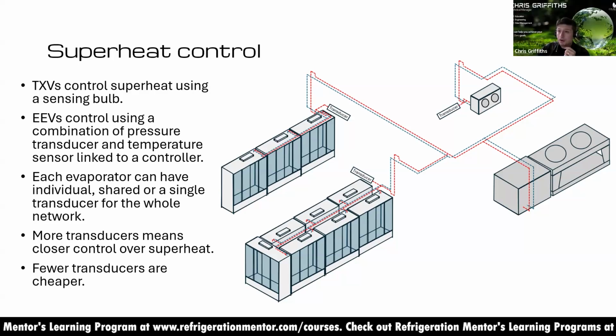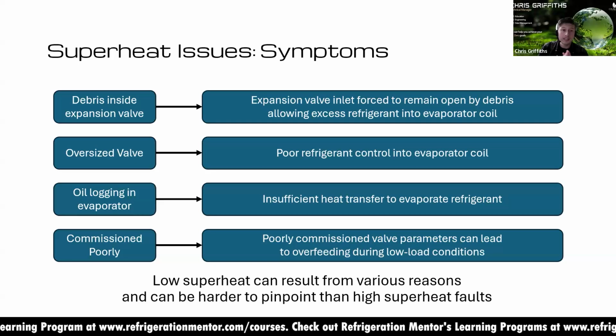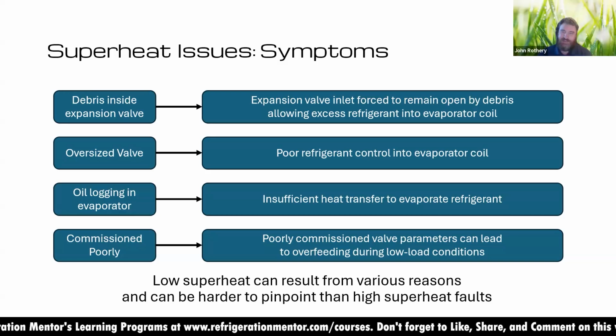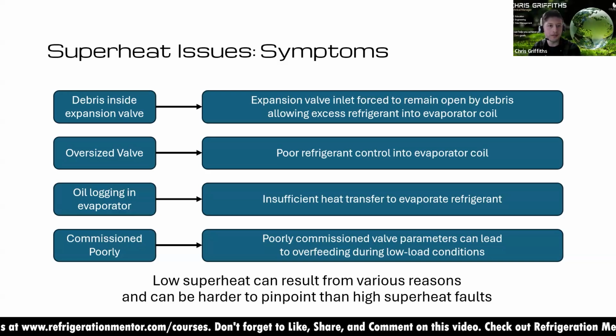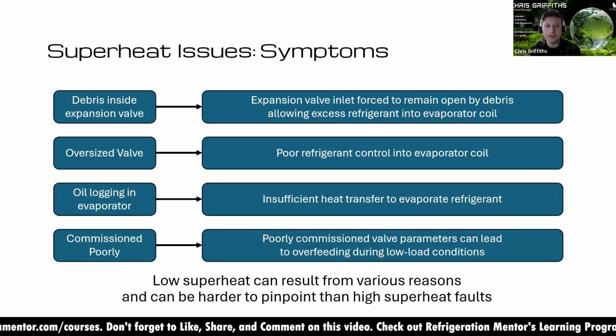Sorry, something just to jump on that, we'll look through it in a minute, but one of the issues we've actually encountered in the past is with those controls, sometimes it's buried deep in manufacturer's literature, but say you have a 60 bar transducer versus a 90 bar transducer, you need to go into the controllers and set up which type it is. Otherwise it will not read correctly and you will get these funny values and discrepancies. The system just will not work as it should, which can lead to some not catastrophic failures, but definitely some big issues that technicians could do without. So yeah, make sure it's commissioned as per all manufacturers' set points and recommendations. Obviously a key one to drive home.